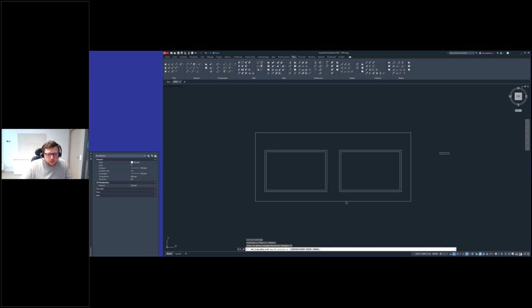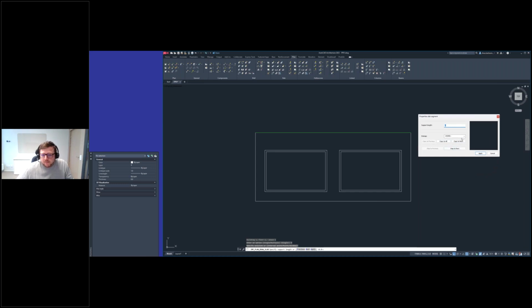I will use my polyline since I have a reference. And either here I can create my end cap, so I can do it later. Let's do it here. So this is the back side. I click here and see, okay, I don't have back here as I created. The reason for that is that the filtering of end caps comes from the definition.